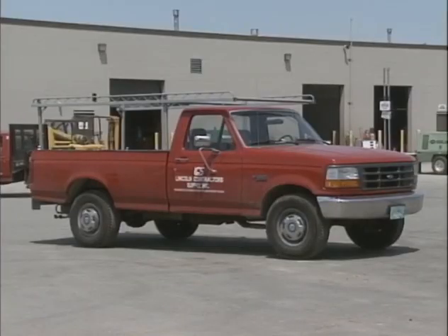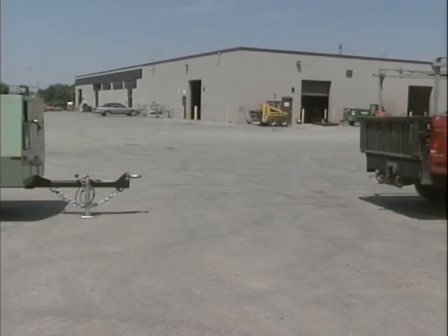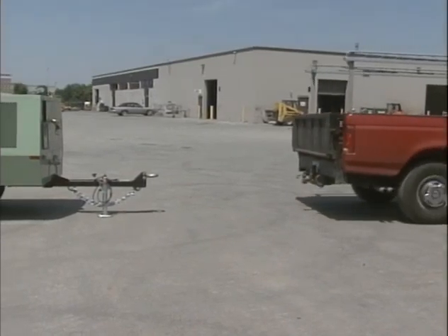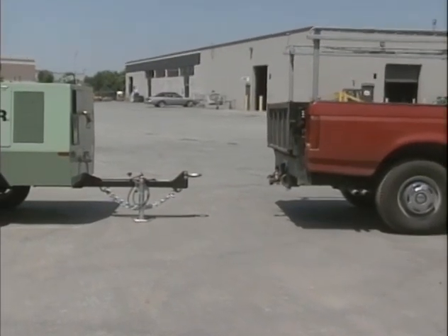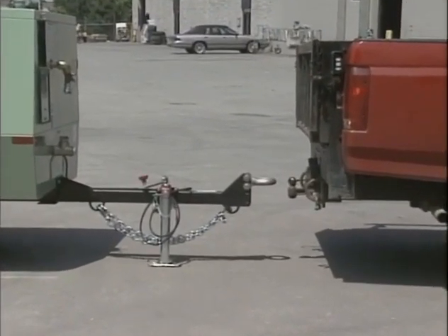Make sure the towing vehicle and its coupling device are rated for towing a vehicle of at least the net weight of the air compressor plus an additional 10% allowance for the weight of mud, snow, ice, or stored tools and/or equipment. After making certain no one is in the way, back the towing vehicle to the air compressor and position it in preparation for coupling the air compressor.